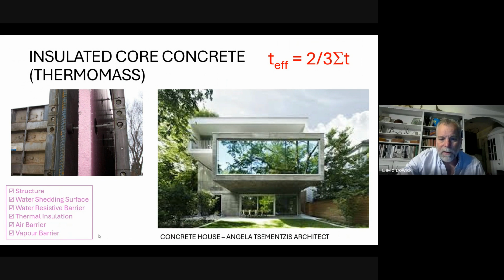So how does that all work? This is a mass system, or a storage system, or a mass storage system, which is the term that I incorrectly use. It is not a rain screen. See, the layer that we do not have is a drained cavity in this wall. So water hits the surface of the wall.